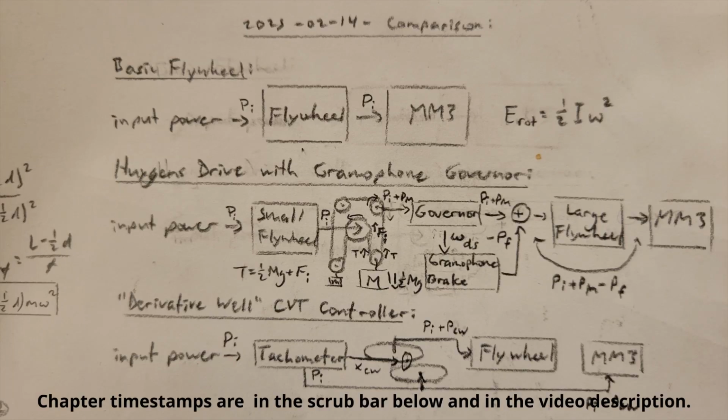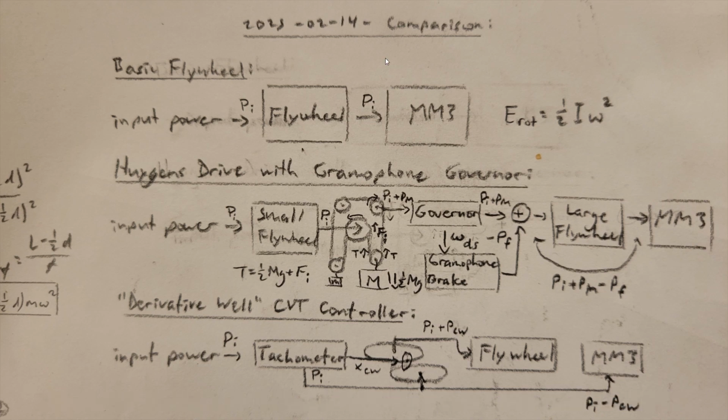Hello, I will now present the advantages of my CVT design on the basis of how system speed is affected by changes in system energy. When analyzing the MM3 system, we can regard it as a collection of different masses of a certain inertia, in this case the flywheel and the programming wheel, whereby the most important concept is that the total energy in the system, measured in joules, is related to the square of the angular velocities involved, where the angular velocity is what we're using to refer to the speed of rotation of the components.